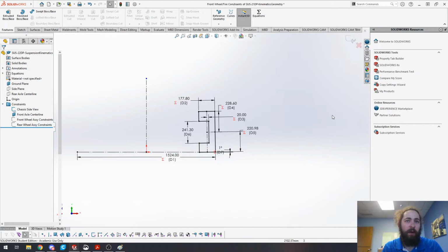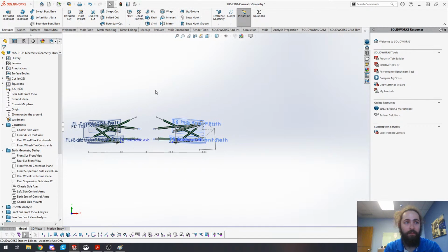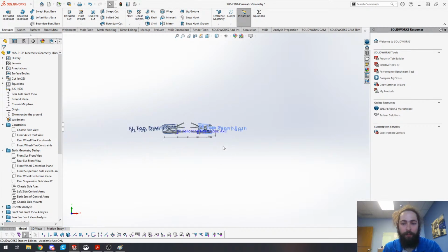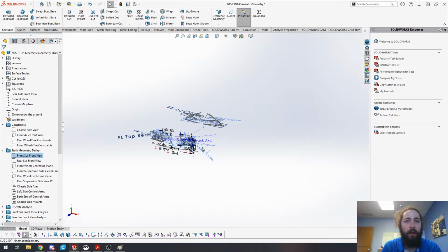And let me just again pop back over here. You can exit out of the sketch. And then I'm not sure if all of you are familiar, but what I just used there was the D key. So when you have those buttons up here at the top right section, the exit sketch and the close, you can use D to bring that right to your fingertip, kind of like the S key fly out.